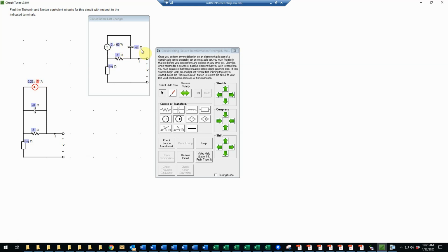And then minus j8, that corresponds to a phase angle here of negative 90 degrees. So if I take this and divide by negative 90, that means adding 90. So that would give me 60 plus 90 is 150 degrees. So if you're not comfortable, you can always use a calculator, but in this case, I can save doing that by doing it in my head or on paper. Okay, so let's check that.